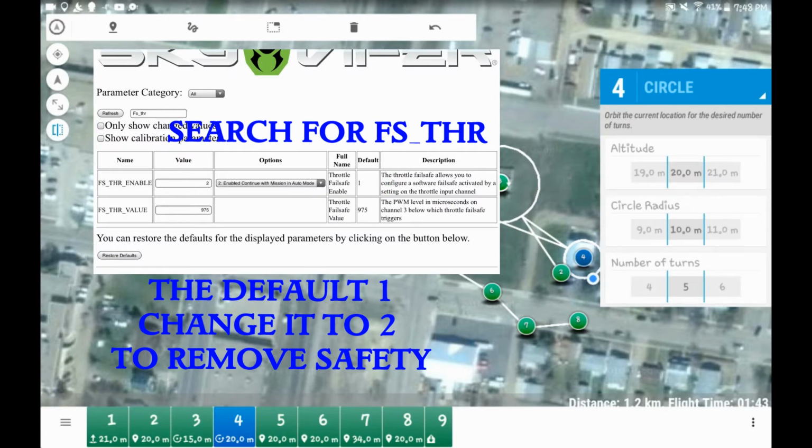And when you turn off that safety, the drone will lose signal with the remote, and the remote will start freaking out and beeping and flashing between indoor and GPS mode. Always fly in GPS mode, by the way.